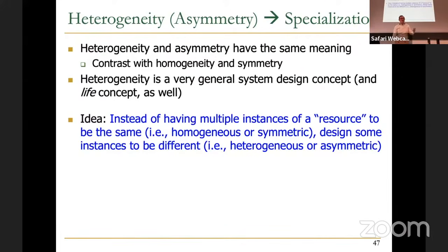The question is, are you exploiting it in a heterogeneous manner? And we have seen that in refresh, retention-aware intelligent DRAM refresh. You refresh the cell according to its leakage. So now that's a method that exploits heterogeneity to gain benefit, which is energy, power, performance, quality of service.